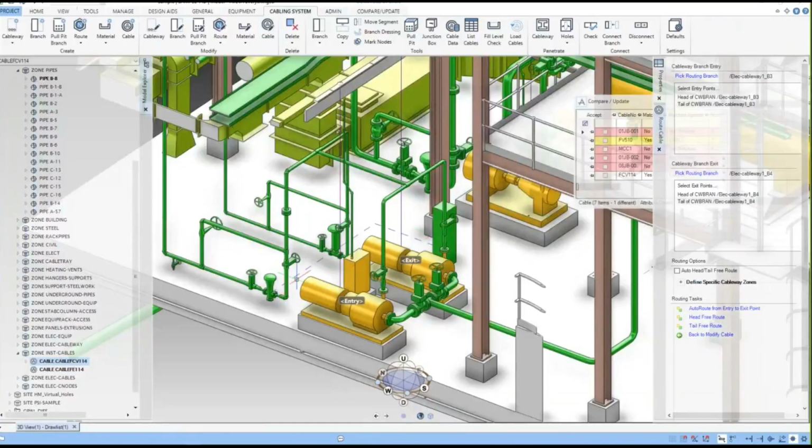You can just see that it's put a cable in the model. So what it's done is run the cable from the control valve to the junction box. Now we can take that information back into instrumentation with the actual length, or even if it's electrical, and they can redo their calculations based on the length. So I'm hoping from this presentation you've seen the benefits of data centricity, how we manage change across the disciplines, and how the integrity of the data is improved.